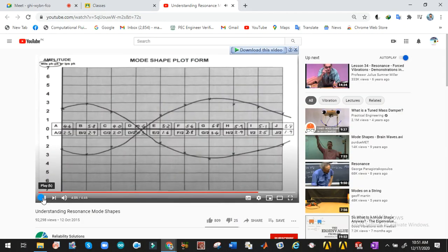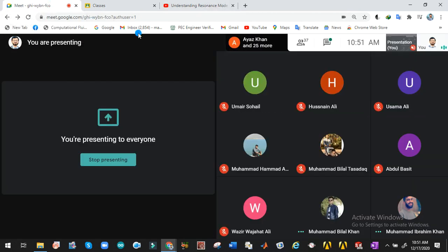So that's resonant mode. You people have seen that when we provide a proper support at the antinode point, the problem goes away. That's why we are always interested in finding the mode shapes, and it helps us solve various resonance problems either by providing damping or stiffness elements.